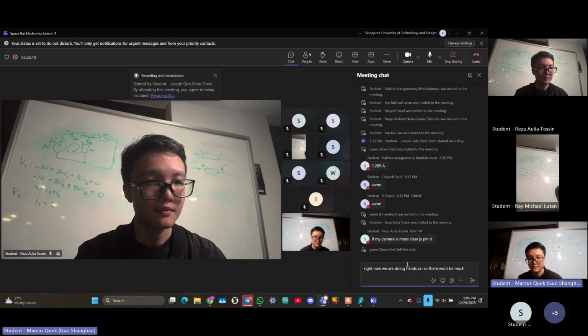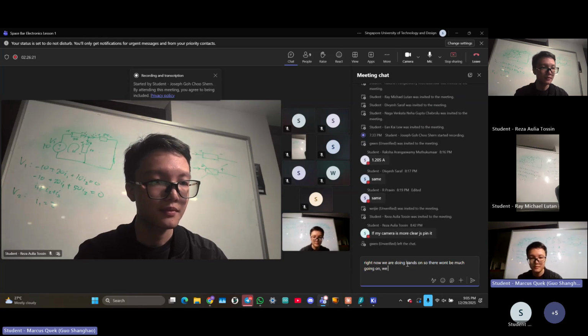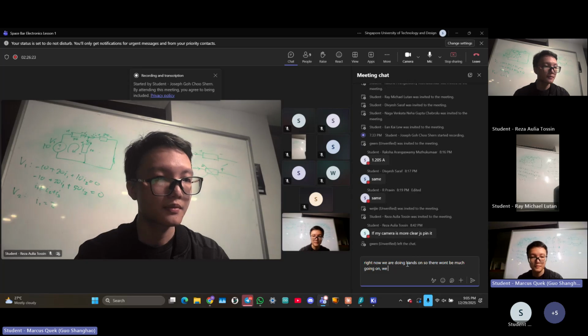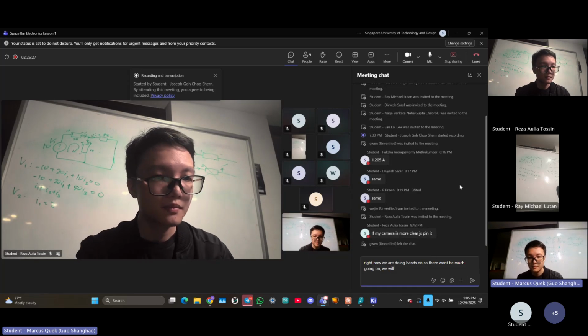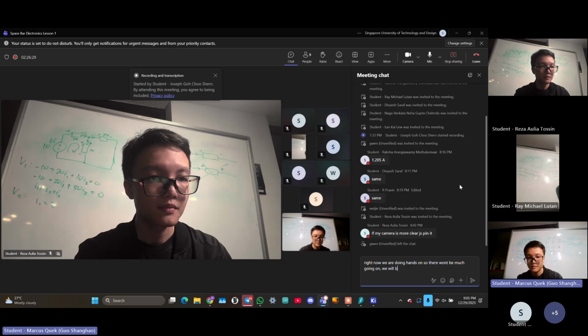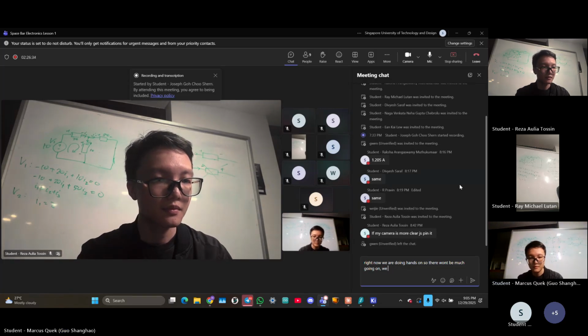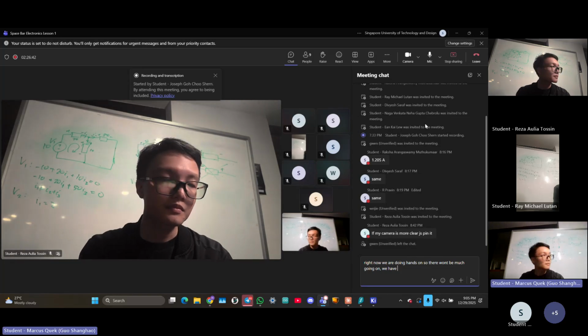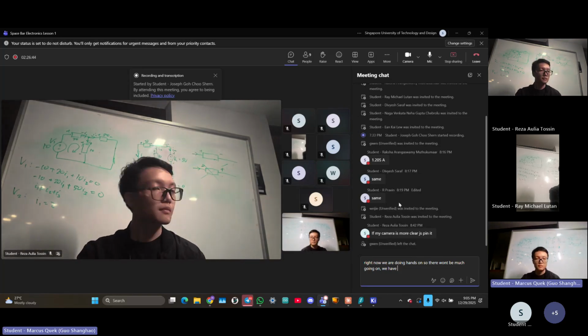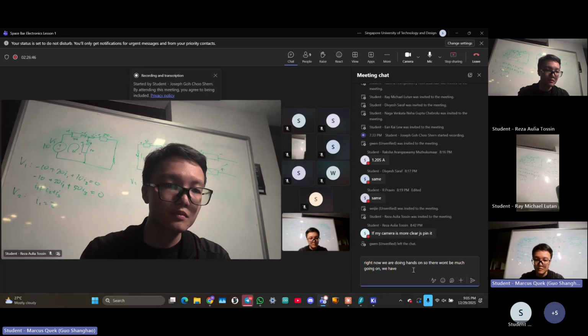I have LEDs. I have jumper wires. Might as well use a nice one. These jumper wires are male to male. You have male to male, female to female, and male to female. Female means there's a socket. These are female wires, and the male can plug into the female like this. Breadboards are entirely female, so I can just plug male wires in like that.